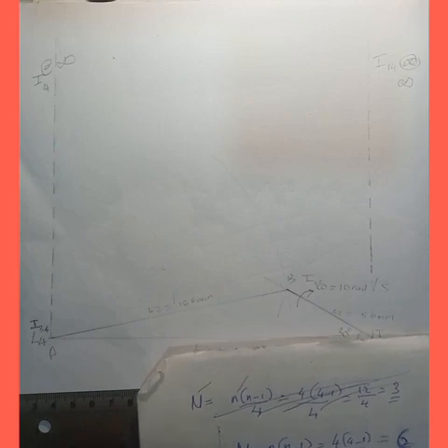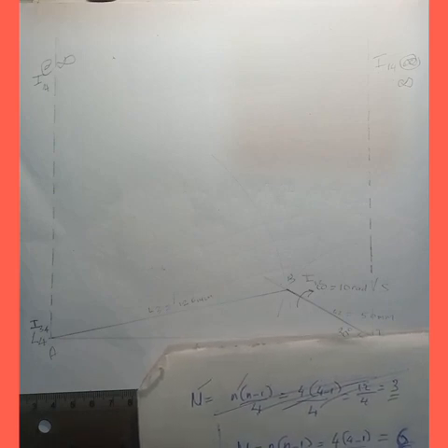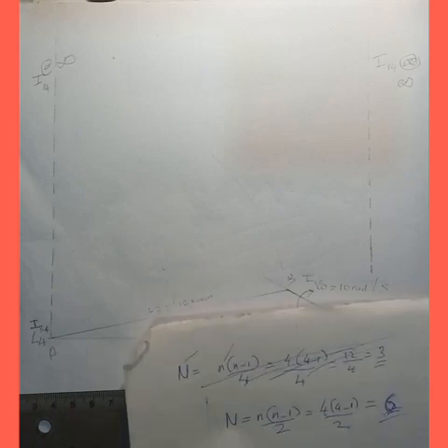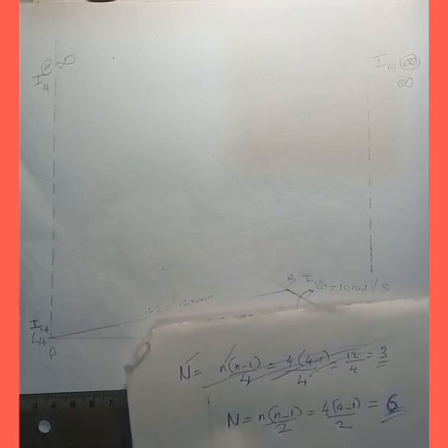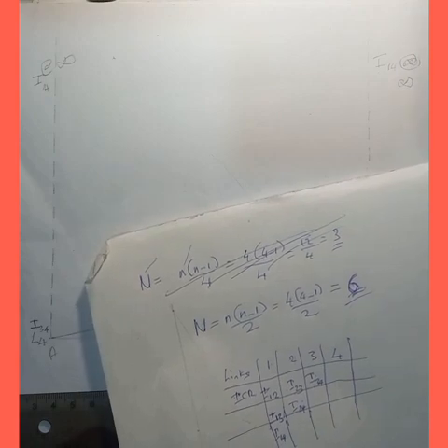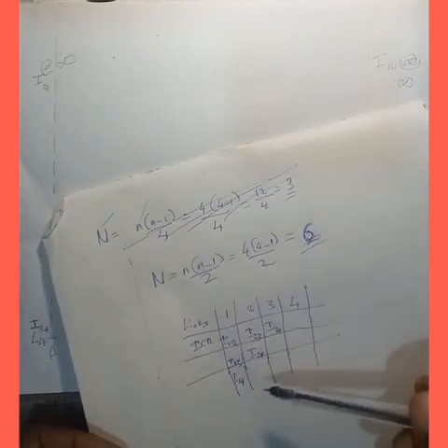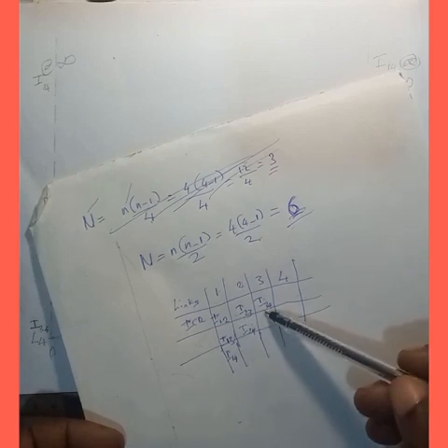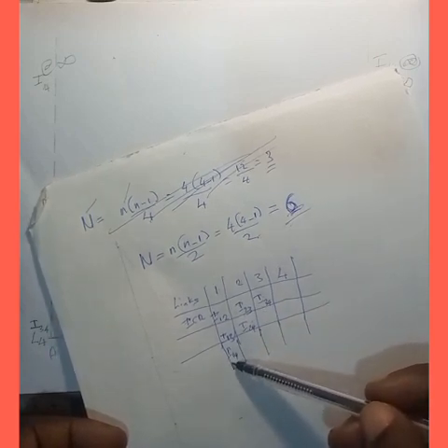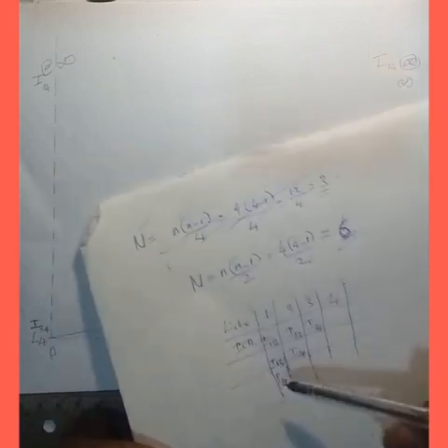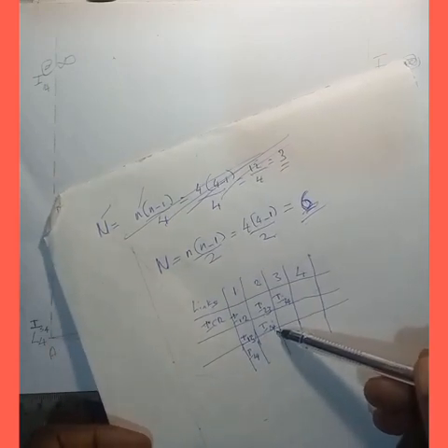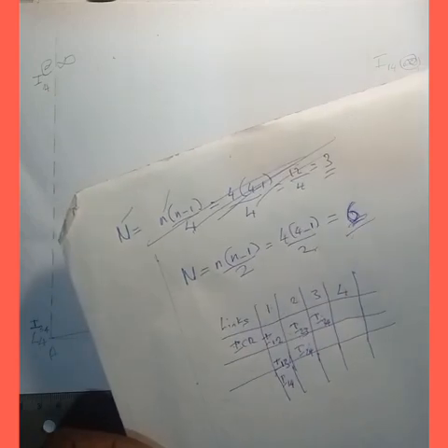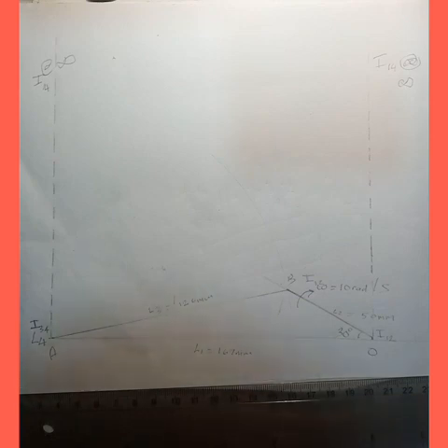Okay, so now coming back to the table, we've been able to locate I12, I23, I34, and then I14 by observation. So we are left with I13 and then I24. So I13 and I24 are called the neither fixed nor permanent instantaneous centers.